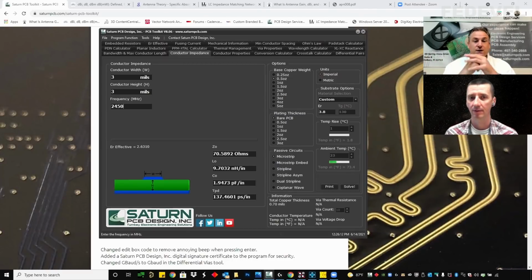Well, it's designed to be consistent. I'm not a chemical engineer for Rogers, but I know that it is designed specifically to be consistent from batch to batch, and from the lower right corner of the panel to the lower left corner to the upper right corner of the panel, which I would also see in FR4. I would see variances on the same panel, just from the way the glass weave is pressed or heated up or manufactured at the factory.